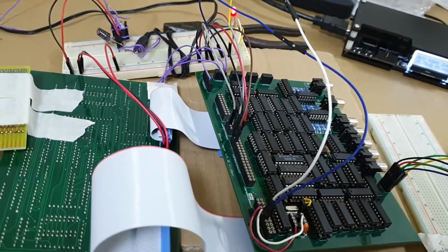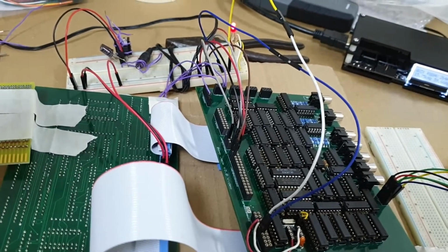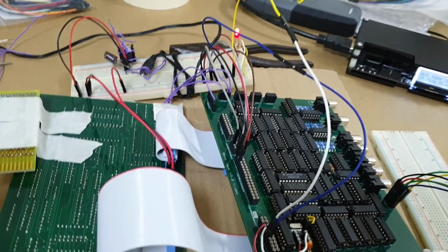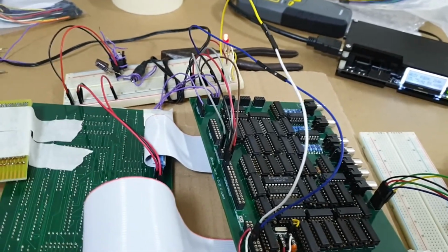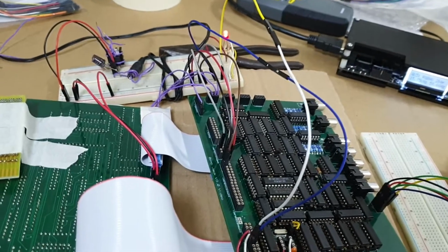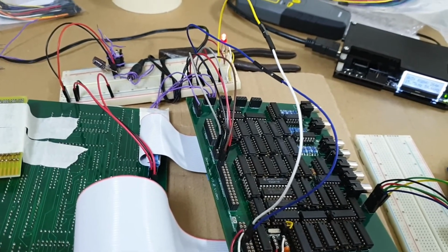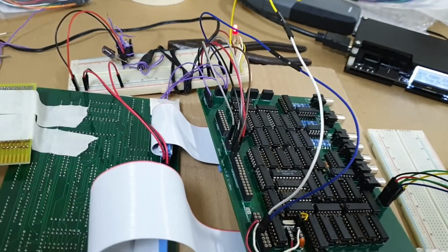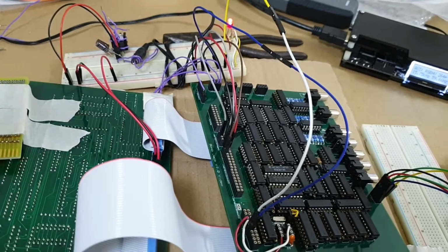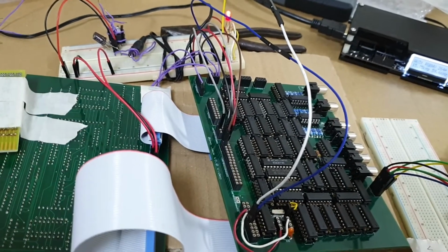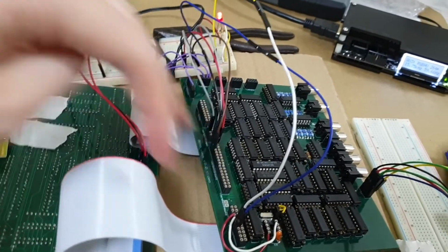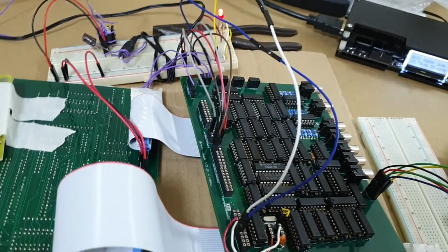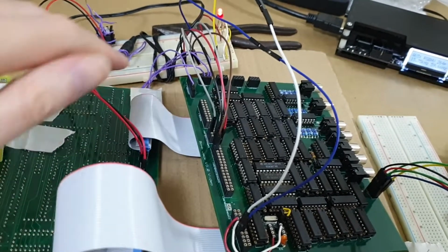I know from when I've been doing some reading on this, I get some kind of feeling about how difficult analog interactions in digital electronics can be, especially at relatively higher frequencies. And 12 megahertz is not that fantastically fast, obviously, for modern electronics, but for through-hole soldered up components, 12 megahertz is maybe starting to get into the range where I need to start really thinking about proper power plane separation, return paths, location of headers. I've put them on the edge of the board because it's easier for access. And I was just reading something today about a happy accident that putting headers on the edge of the board is really good because it helps to separate out your signals.